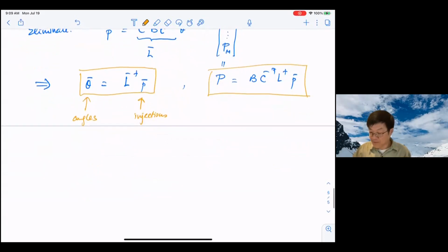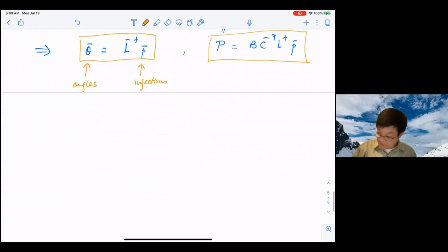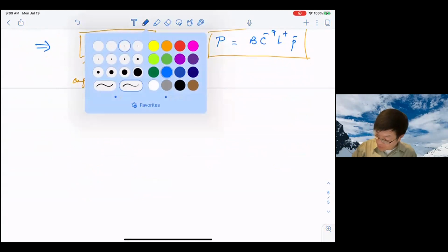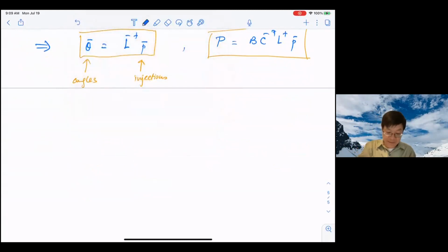So DC power flow, even though it's an approximation, is very widely used, especially in transmission networks. And one example of that, let me see if we have time. It should be fine. Okay, so let me just write that down to show one example. One example of that is what's called economic dispatch or DC power flow. This is the problem of, given loads in the transmission network, we want to schedule generations, the bulk generators.